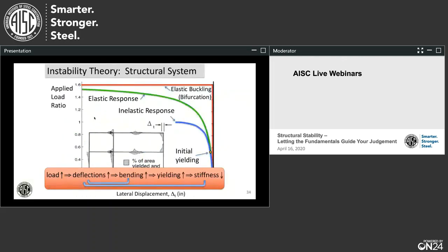One more time, this is certainly the same situation with a structural system. So I've got a little two-story, two-bay frame down at the bottom here. And in this case, all I'm doing is putting on the gravity load. And if I did a bifurcation analysis, nothing would happen to that frame, and then suddenly it would buckle. On the other hand, if I included an initial imperfection, or even, interesting for this frame, because I put on gravity load on a non-symmetric frame, right from the beginning it starts to lean anyway, so I don't even need an initial imperfection.